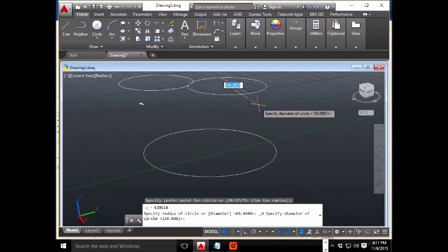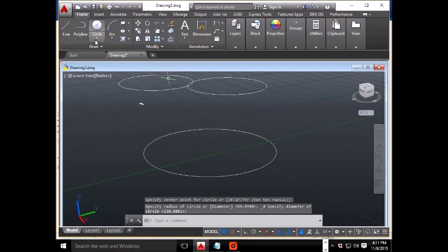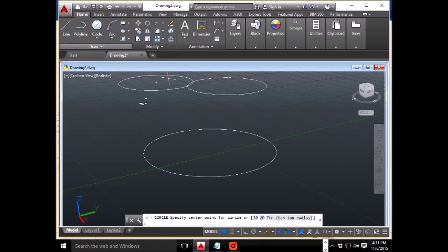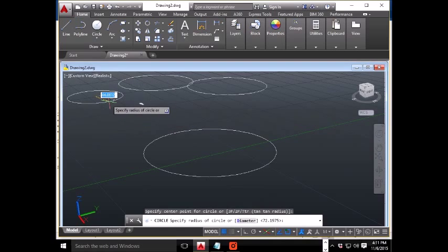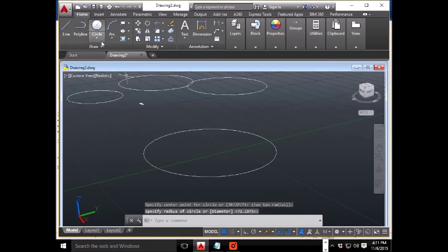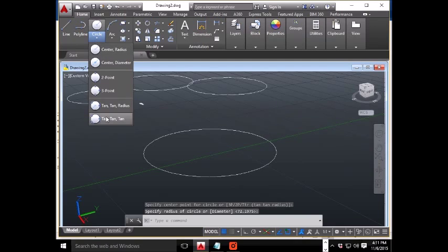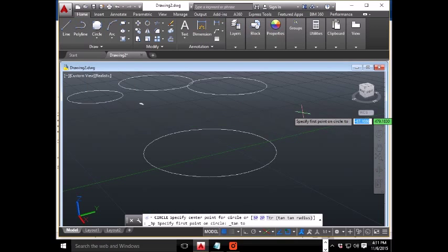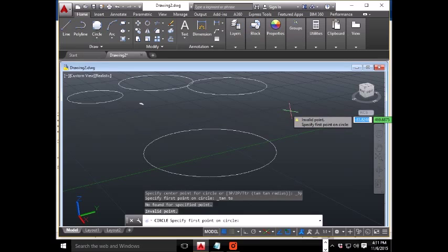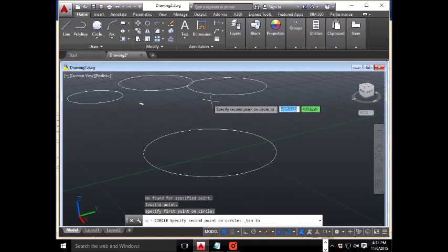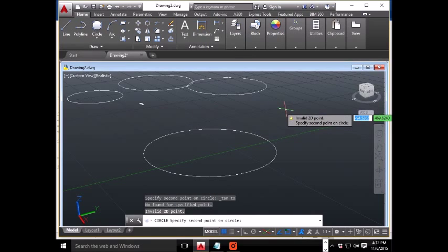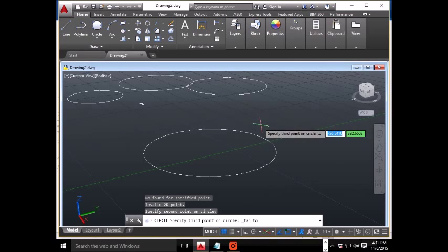A 2D isometric drawing is a flat representation of a 3D isometric projection. This method of drawing provides a fast way to create an isometric view of a simple design. Distances measured along an isometric axis are correct to scale, but because you are drawing in 2D, you cannot expect to extract other 3D distances and areas, display objects from different viewpoints, or remove hidden lines automatically. By using the isodraft command, several system variables and settings are automatically changed to values that facilitate isometric angles.